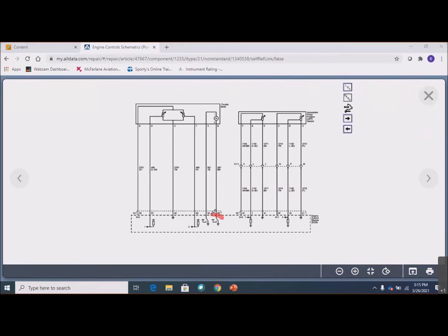There's a pair of switches, and are they really switches? Are they mechanical contacts inside the engine control module? Of course they're not, but they're the electronic versions of that. There are no actual moving parts, so they're basically transistors. And notice that one pin of the motor, pin 1, goes right to the engine control module, and so does pin 2. There's nothing in the way.